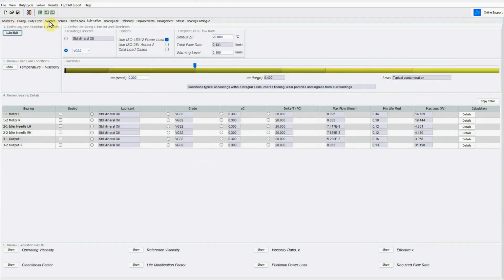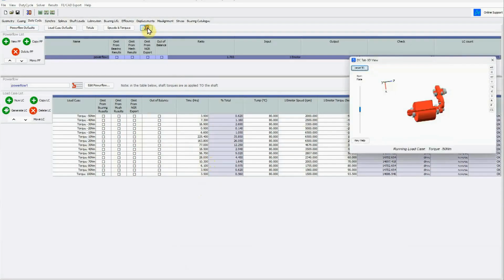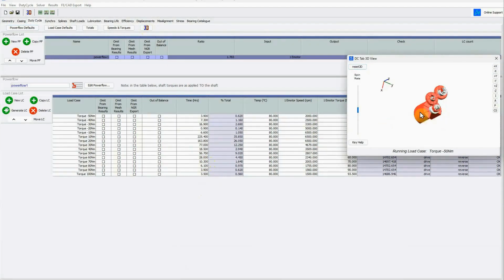And then the required life at each of these operating conditions is divided into the calculated life to give a damage figure. And these can be summed using the Palmgren-Miner theory to give an overall damage. 100% damage, for instance, equates to a 10% failure rate.